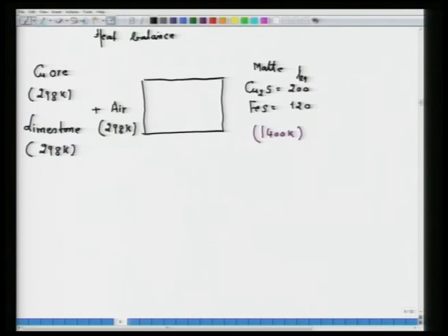Then the slag amount we have to write down, FeO, SiO2, and calcium oxide. So, FeO is 287.5, I mean they are all in kg, SiO2 220.0 kg, and calcium oxide 82.6 kg, and it is being discharged at 1400 Kelvin.